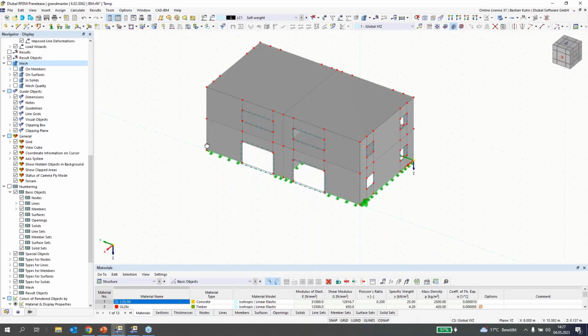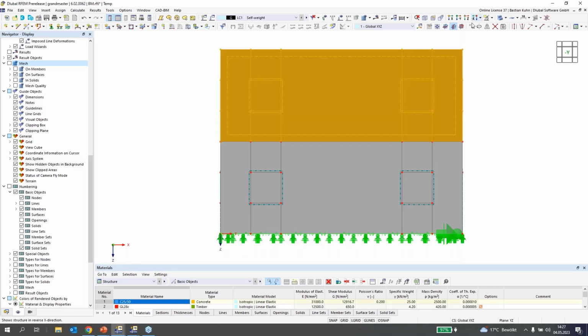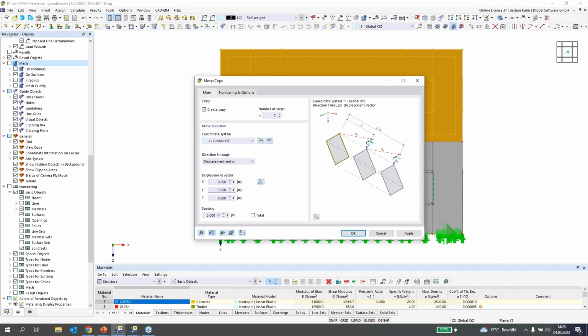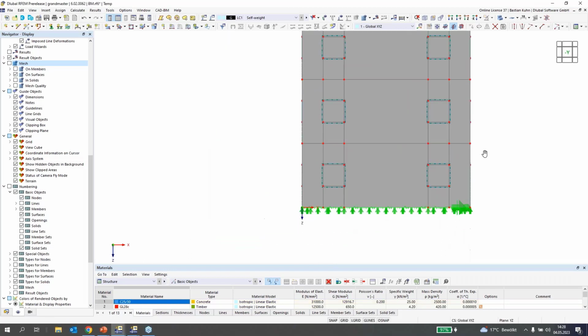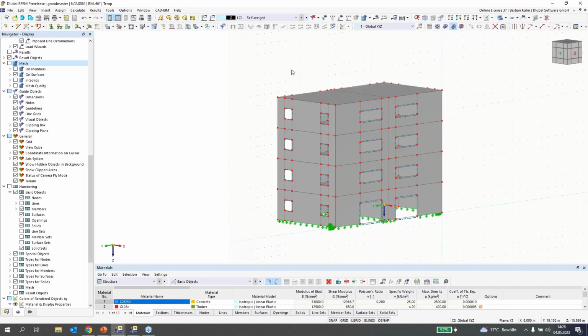Okay, and we will now copy the missing 2 stories. Via here, now we can use 2, and then there's Y0, and here minus 3 meter. That's okay to delete the mesh. So you see, that's it. We will put some supports we did. We will put some force from self-weight to it with a value of, let me see what I choose here, just that your downloaded file contains the same load, 2 kilonewton per square meter.